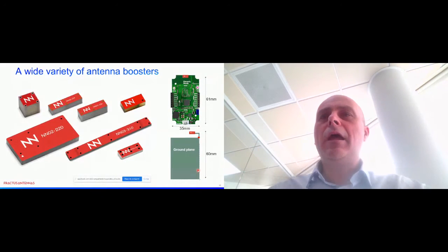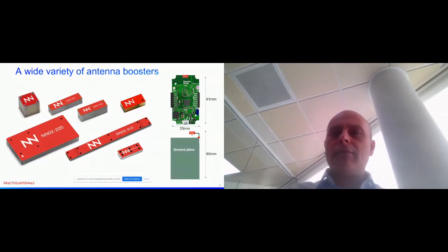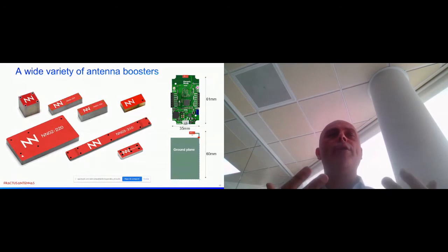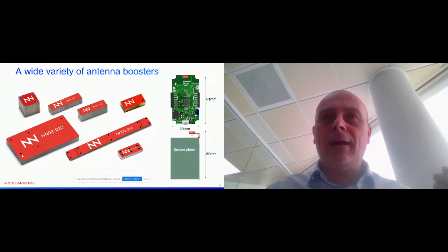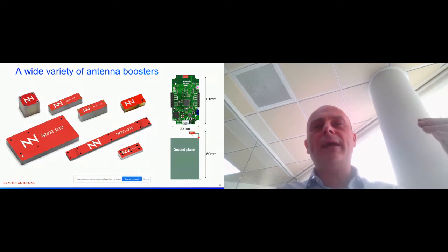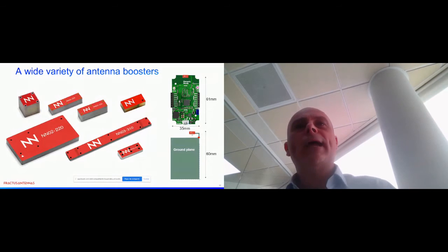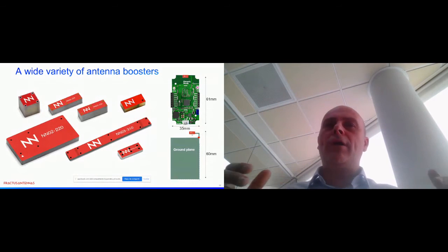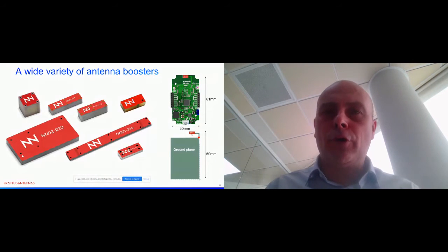It's very similar with an approximate position of the antenna booster. And once we select this, what we obtain in return in this library is an S file containing all data from a very low frequency, 0.6 GHz, up to 10.6 GHz. So you can play with LoRa, or perhaps you can play with other protocols.